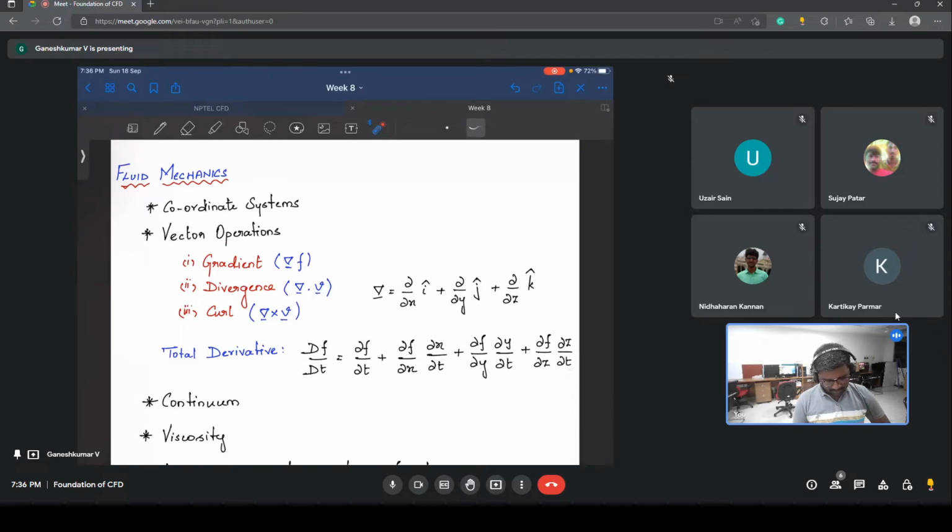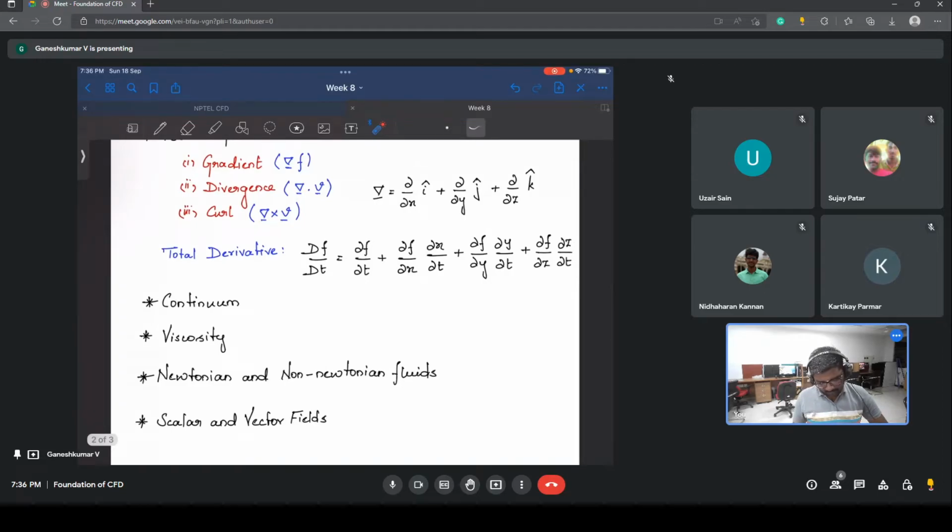So this would be the total acceleration. Then you will multiply by rho, which becomes m times acceleration, which is equal to all the other forces like the pressure gradient. So basically the momentum equation is nothing but F equals ma. And we also saw continuity.